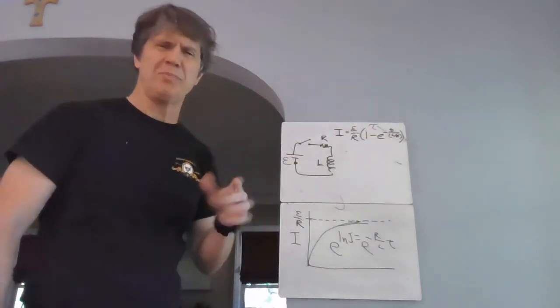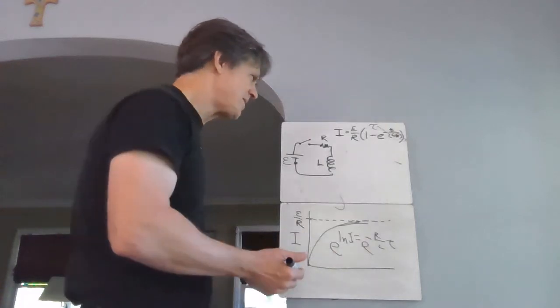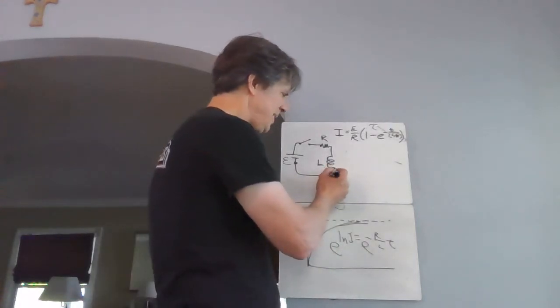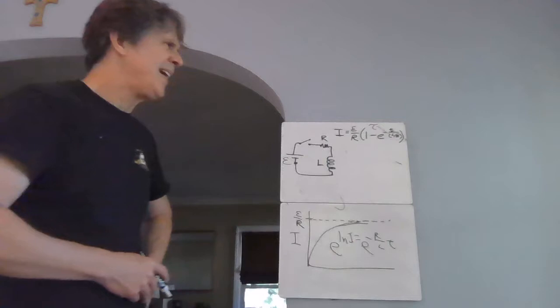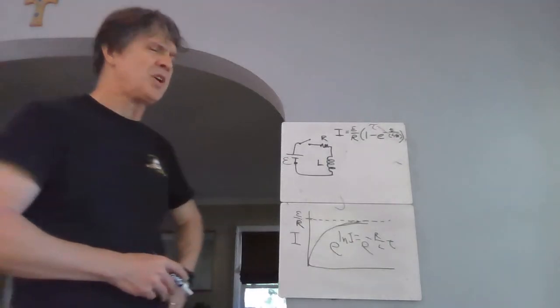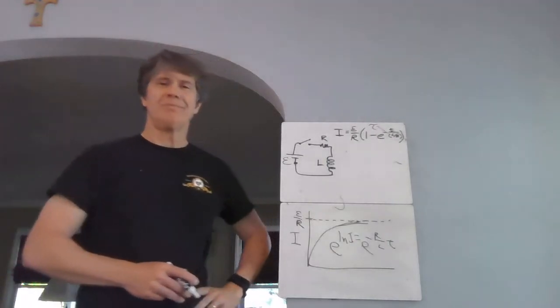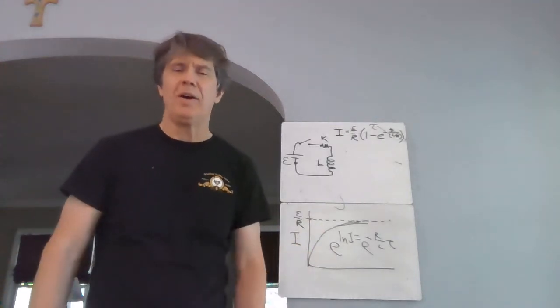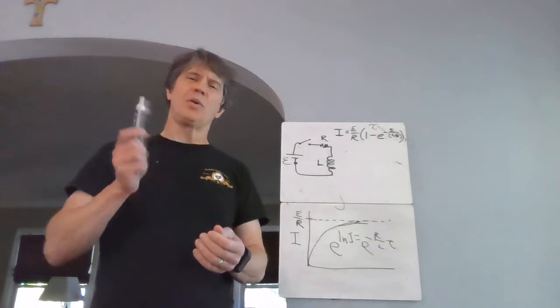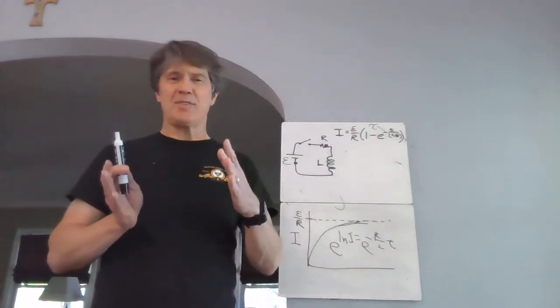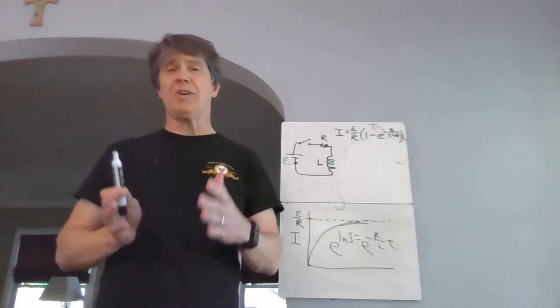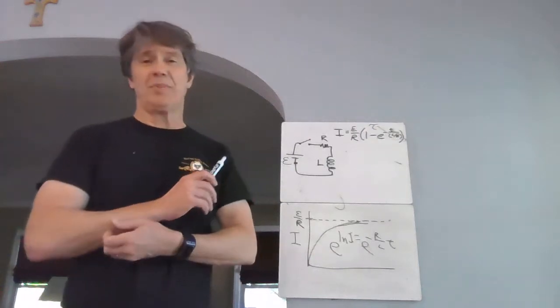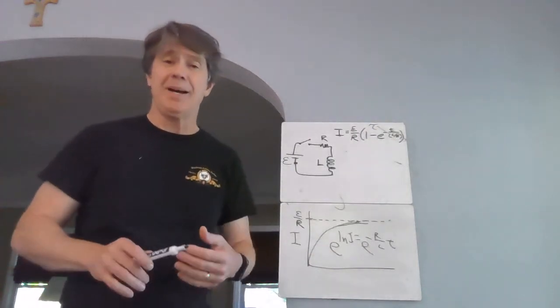Let's brainstorm through that just a little bit here. So why would it take longer to charge up if it's more of an inductor? That's easy. It fights the change more. More of an inductor, like with more coils wrapped up, has more ability to fight changing currents. It produces more of a flux and more of a changing flux and more of a back EMF.